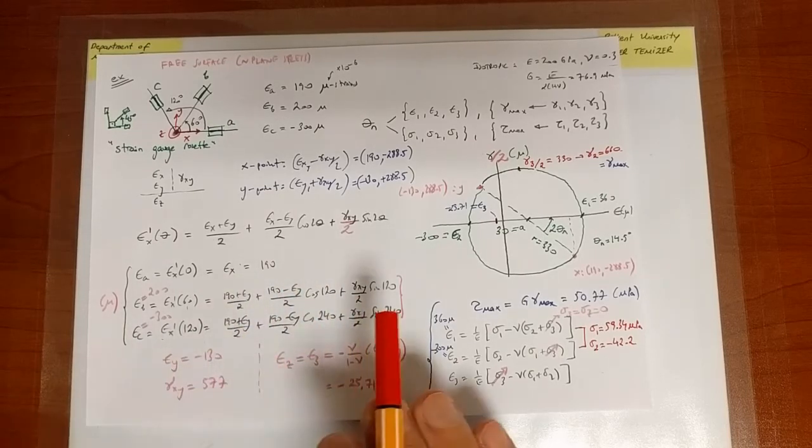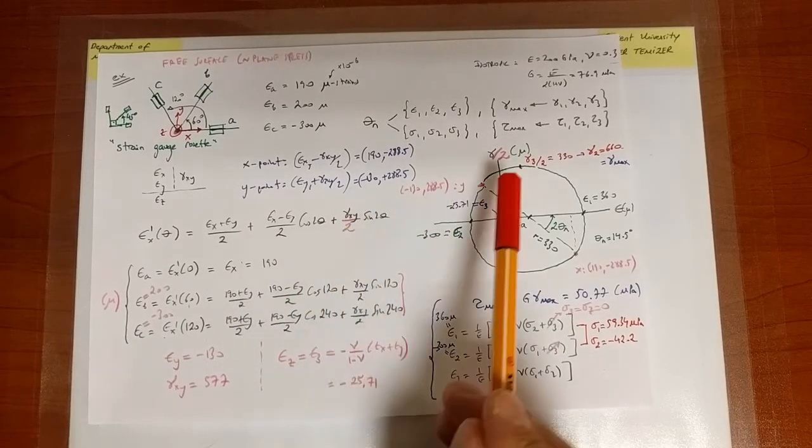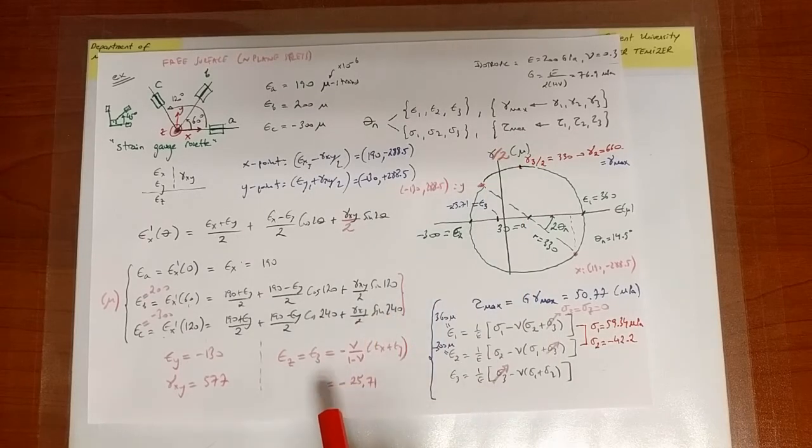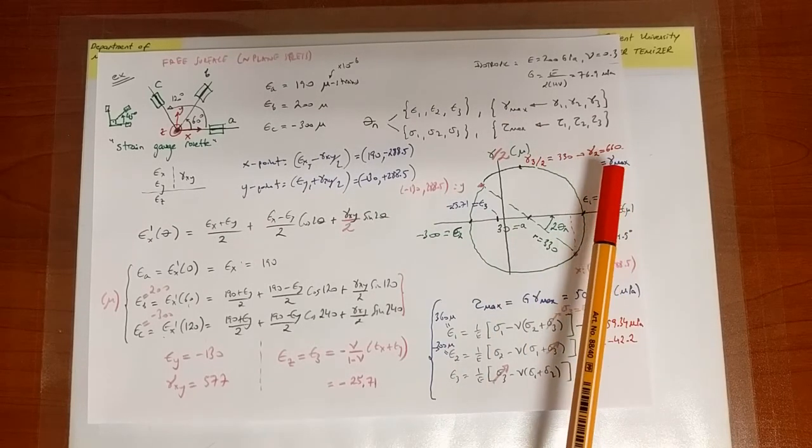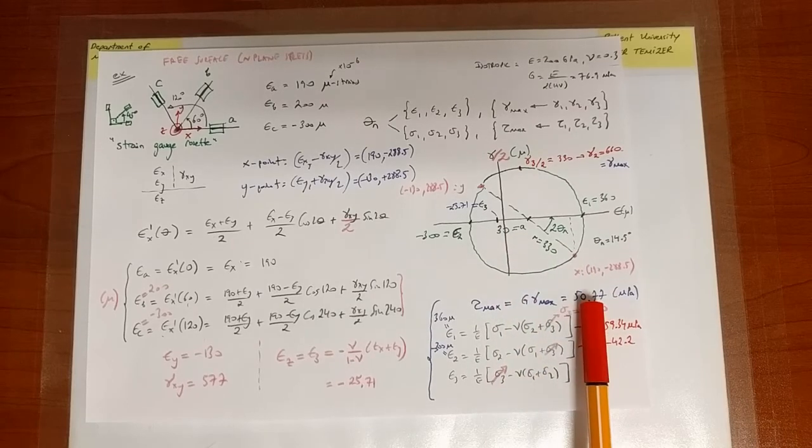And the idea is exactly the same as for stresses, except for that factor of 2 that we must remember. And ultimately, we have also brought together many concepts that we discussed before, like the relation between stress and strain. Remember again, why are we doing all of this? Why is this a nice example? Because we want to know at a surface of a structure, because let's say we suspect that it's a critical point, whether the stresses are close to delivering failure or not, or whether, within a safety factor, I am safe. And so I want to calculate, say, if the material is sensitive to that value, the absolute maximum shear stress.